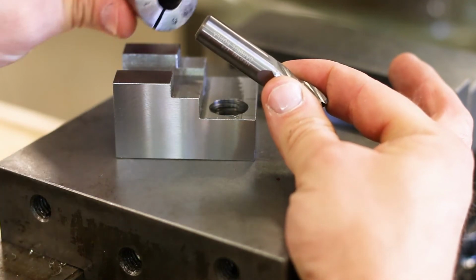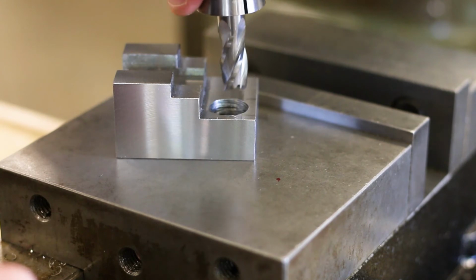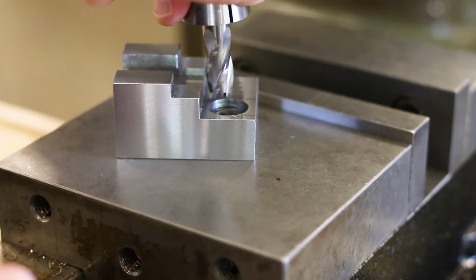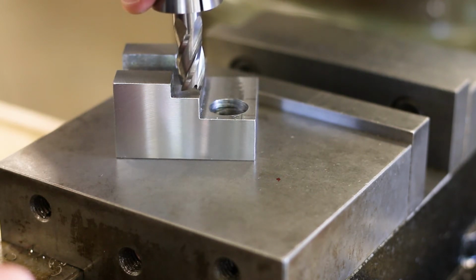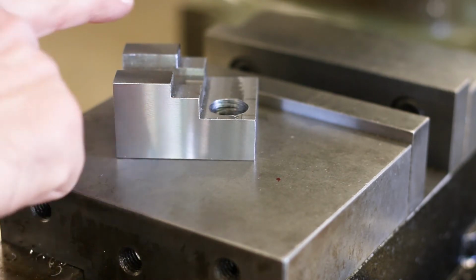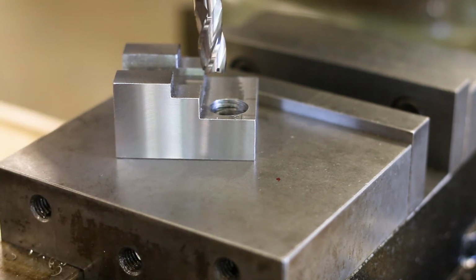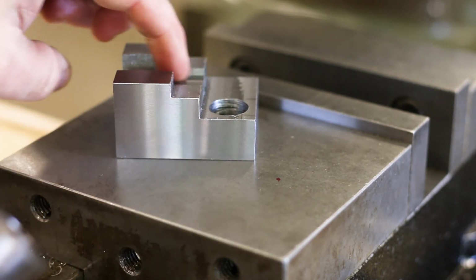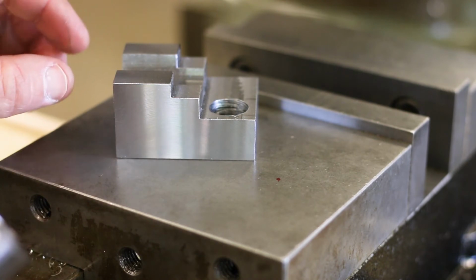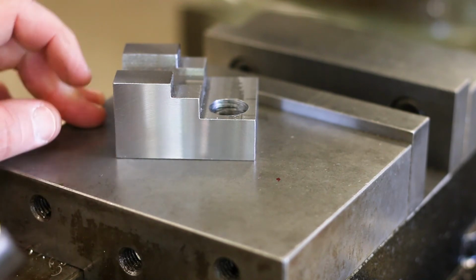It's a 1/2-inch tool, and we're going to hold it in a 1/2-inch collet, like so. So the plan is to finish this first step, both the depth and the width of the step, in, let's say, I don't know, looks like maybe 3 or 4 passes. Then do this next step in maybe 2 passes, and then we're going to do the tops of these wings. That's actually the top surface of the part right there, and that's going to establish our overall height. And then we're going to come in and deal with the slot. Although we're going to talk about the slot a little bit more in depth because there's a little bit of a strategy about how you get the size of the slot and its location. And so we'll just talk about that when we get to it.